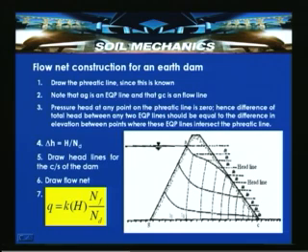So, in this case, if you approximate, there are 2.5 flow channels, and this is the direction of the flow, then they can be numbered in this direction, such that the number of equipotential drops is ND. This is for a homogeneous earthen dam, and we have discussed the method for determining the quantity of seepage passing through the earthen dam.